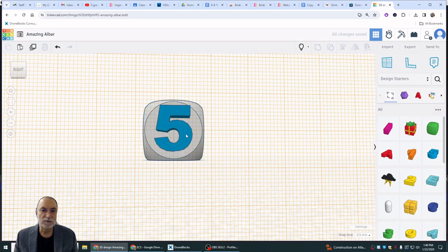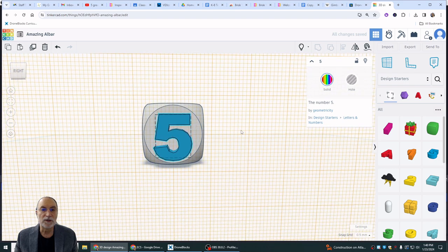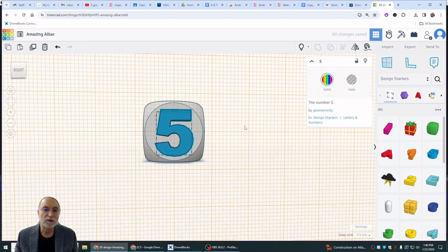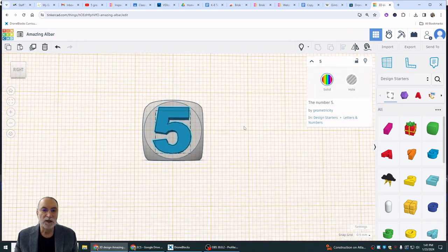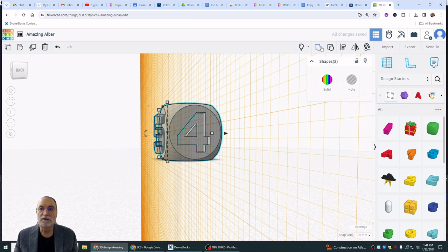I think we can come down just a little bit. I think bringing it down 0.5 millimeter really works good. So let's spin this around, move it into the die 2 millimeters, so we should say -2 here. Turn it into a hole, lasso it, and group it.